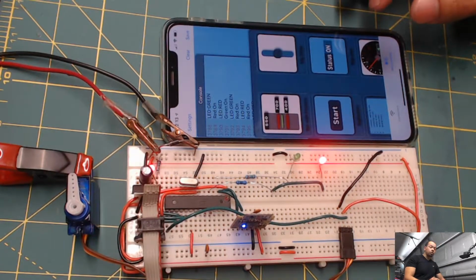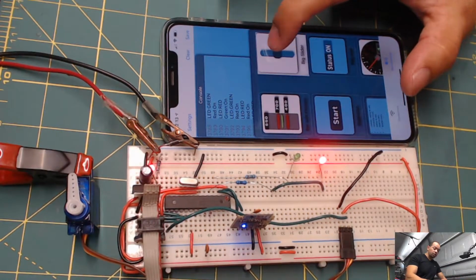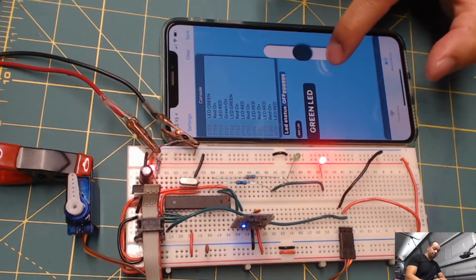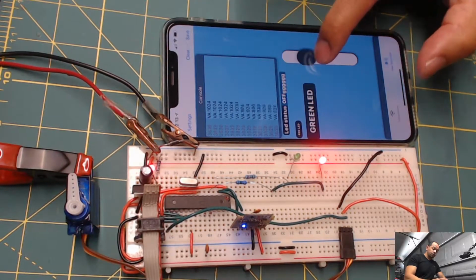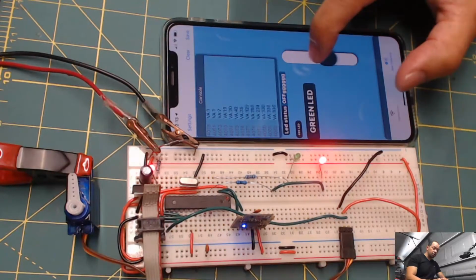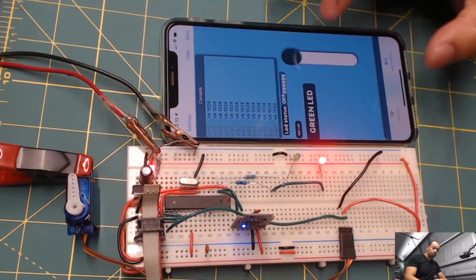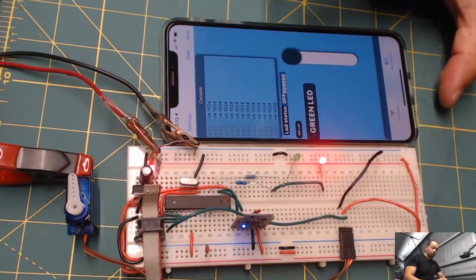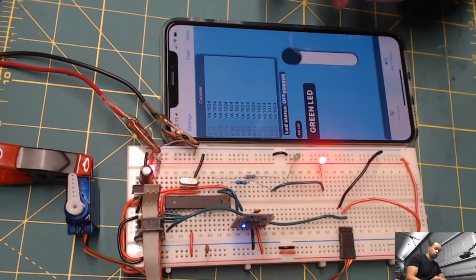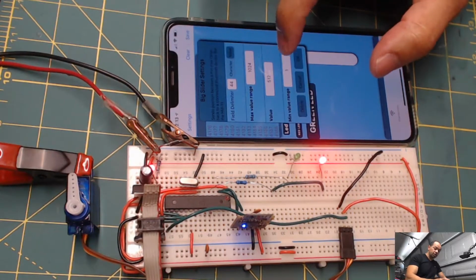Now we are going to control the servo here, and we are going to do that one with this slider. This slider just sends a value back of a specified range that you can change. Right now it's sending from 1 all the way to 1024. The servo is controlled with a value from 255 all the way to 1300. So let's change those settings.